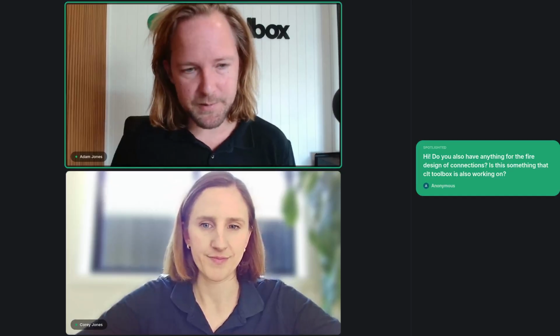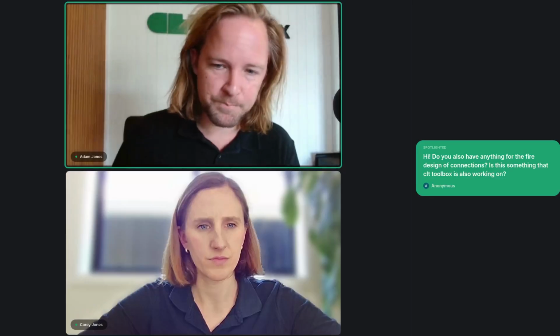Yeah, that's a great question. So we are right now building the char modules like I showed you before as modules. So you'll see them in the first step integrated into our connection details. So, for example, like a beam to column connection, by the end of the year, you'll have charring around that. And then you'll be able to say input a protection system around that to protect the gap or something like that. But yeah, so that's coming. And then the other one over time is the exponential reduction method. We'd love to input from how your actual screw reduces its strength in the fire scenario. So it's a great question.